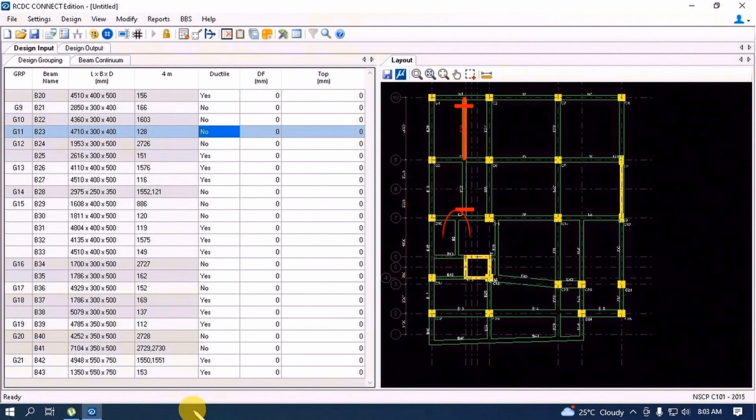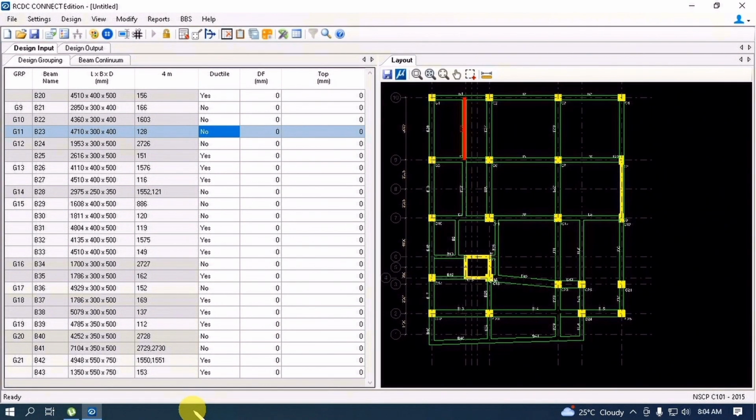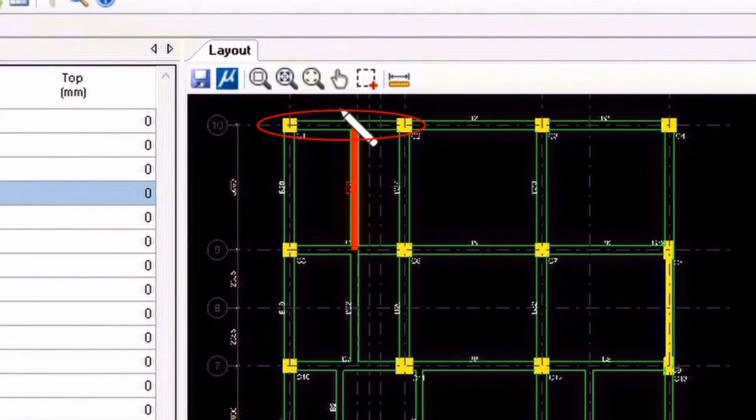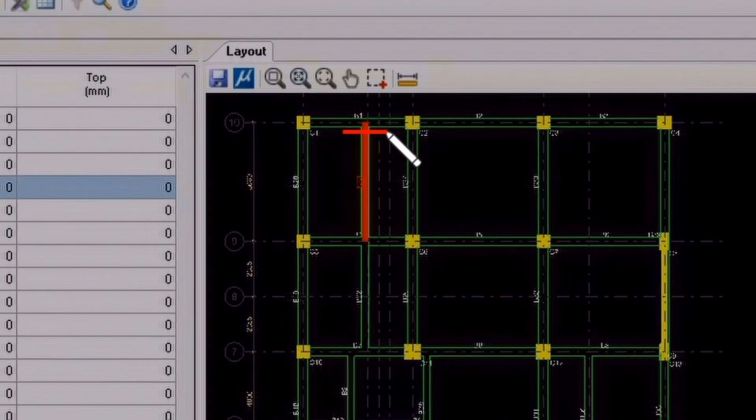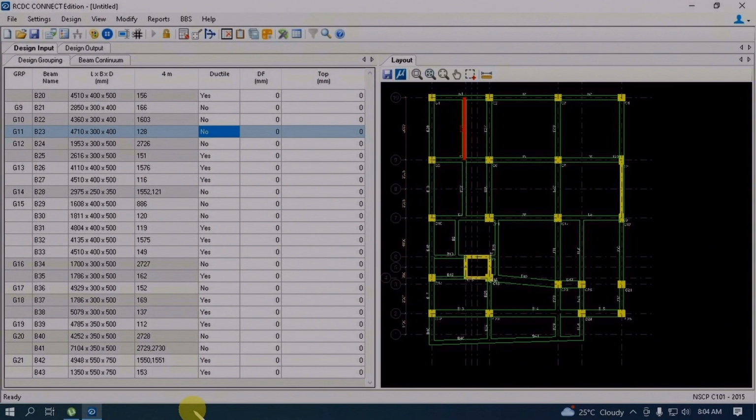We can apply the partial release of moment in its joint connection. You know guys, many STAAD users, whenever they see intermediate beams across the floor framing, will immediately think of the release and partial release command. Do we think this primary beam will fail here if we make this connection fixed? Let us find it out.